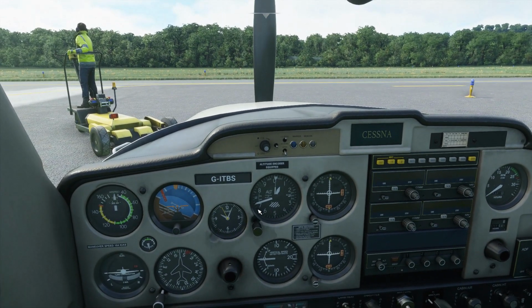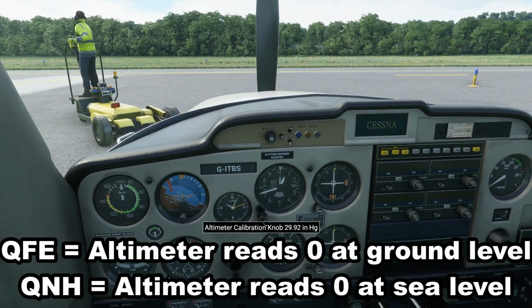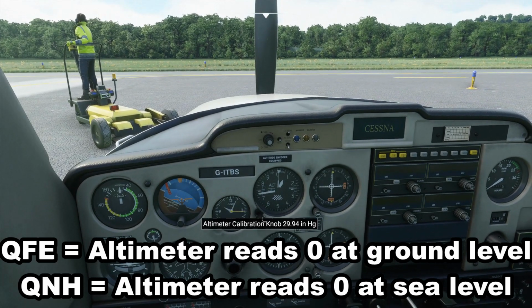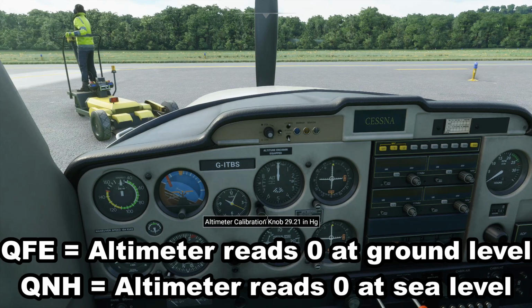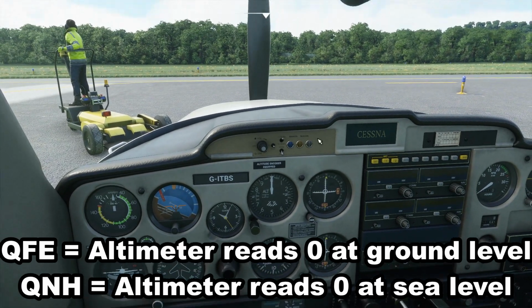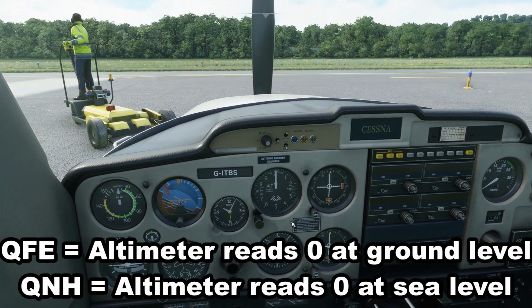So typically we'd either set QFE, which is referencing the altimeter to the aerodrome elevation. To do that we can basically just zero the altimeter. And now we have QFE set, and any altitude that we read off this instrument will be relative to ground level at the aerodrome. Otherwise we set QNH.